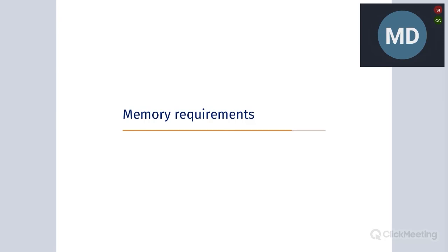And I told you already that there's a significant memory constraint for this system. While in most CFD we try to use different size meshes or higher order schemes, in Lattice Boltzmann you are limited to second order schemes, so you need to go for high resolution meshes.